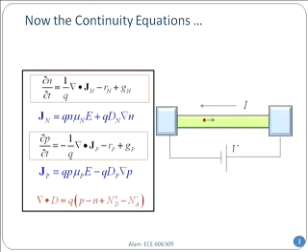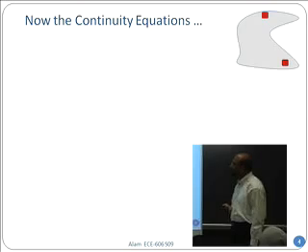But the first and the third equations are conservation equations, valid always, regardless of what detailed physics you put in for Jn and Jp. It's valid always, and let me explain why. Because this is simply a conservation law. So long as electrons are neither created nor destroyed in a global sense, then of course these relationships will hold.